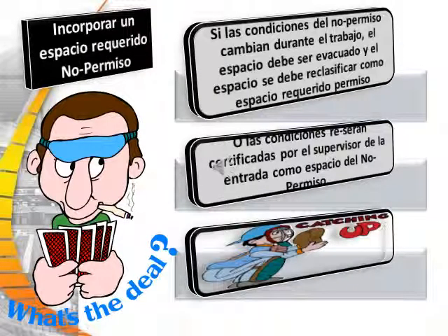If non-permit conditions change during the job, the space should be evacuated and reclassified as a permit-required space, or conditions shall be recertified by the entry supervisor as a non-permit space.